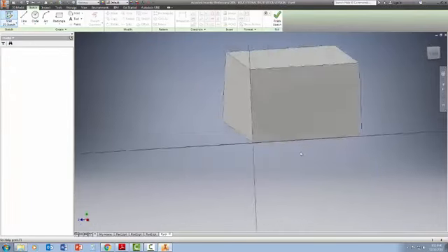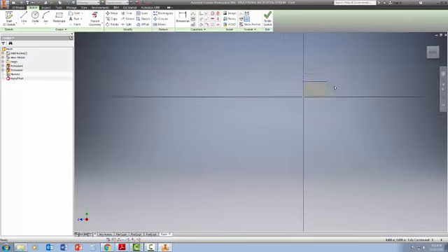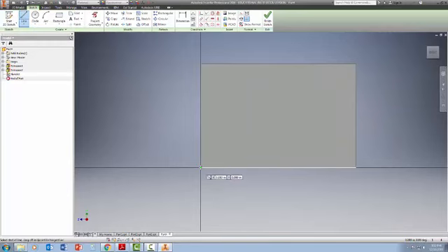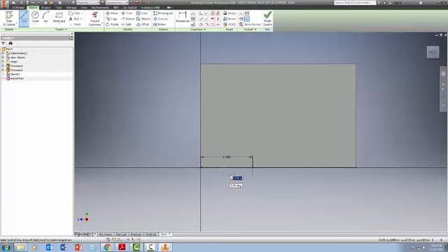And we are on the right side. So let's just start a sketch. And we are going to go from the very, very bottom. We're going to start with a line tool. Line. Click at the very bottom left. Come over 1 inch. Type in 1. Make sure I'm at the right angle. I am. I'm just going to bring this up perfectly 90, not 88, not 86. Perfectly 90 degrees. Bring it all the way up to the top. It should be 2 inches. Click.